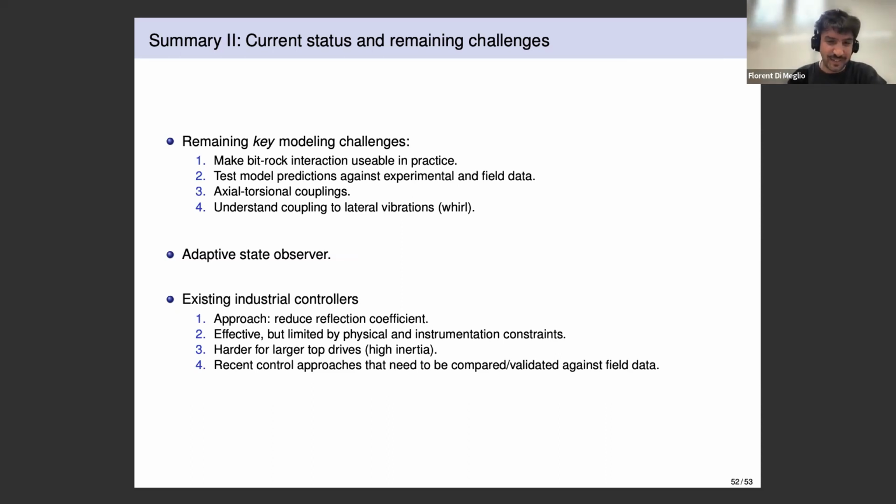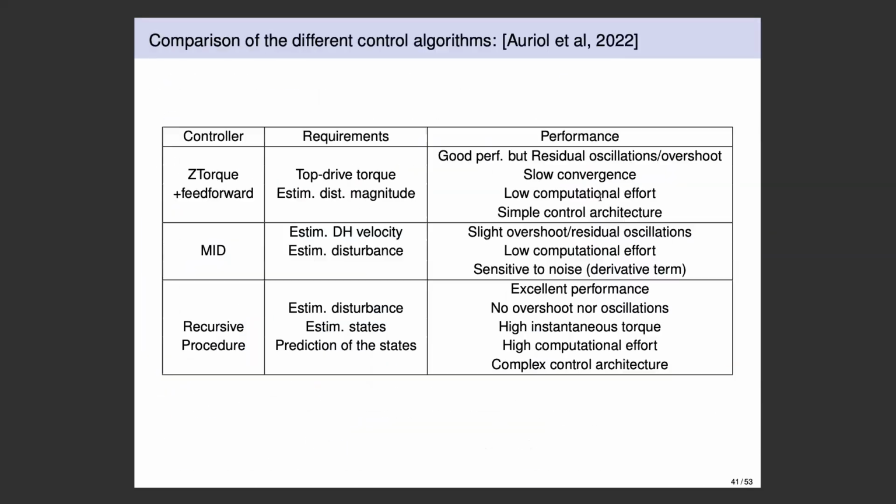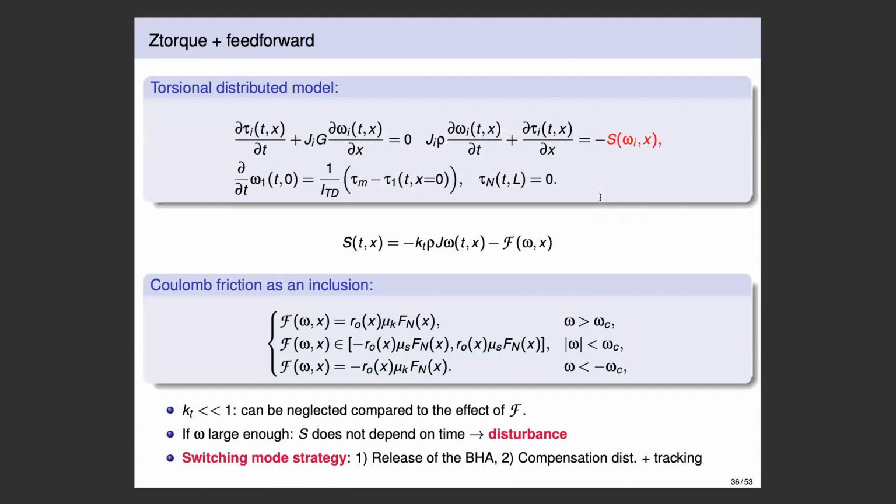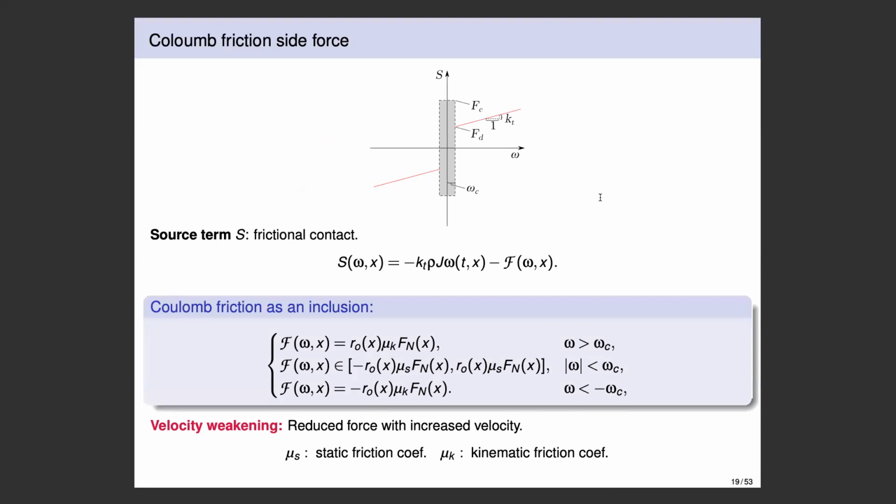I had a couple of questions. You made an assumption on a friction model, that step-type model when you transition from static to dynamic. Have you looked at the sensitivity of that model? I'm looking at that friction model versus others. What made you decide to use that model as opposed to a more typical one with Stribeck effect, or anything else?